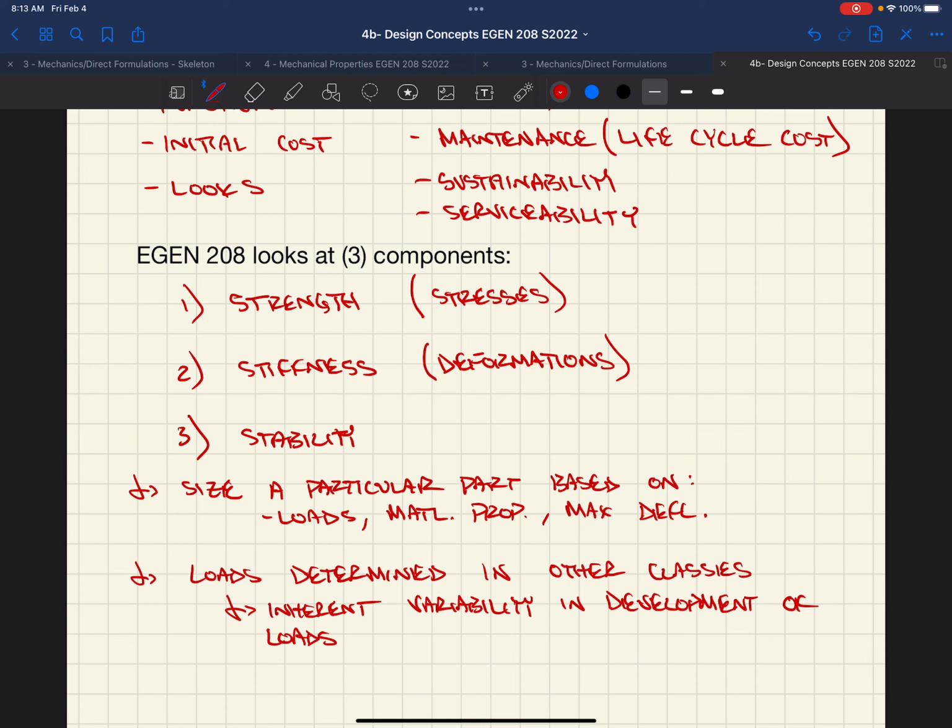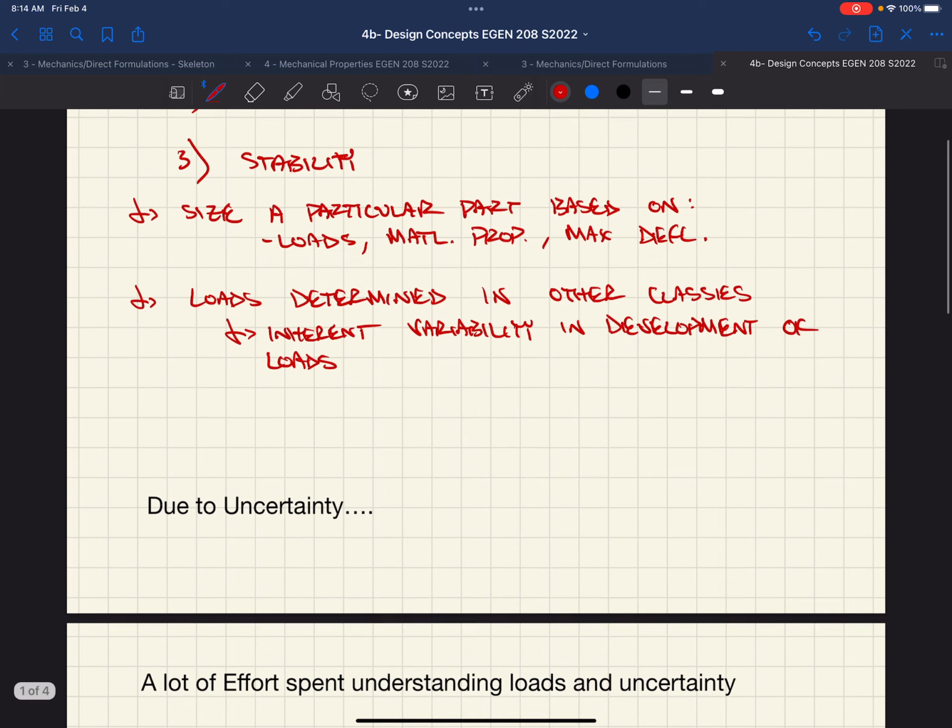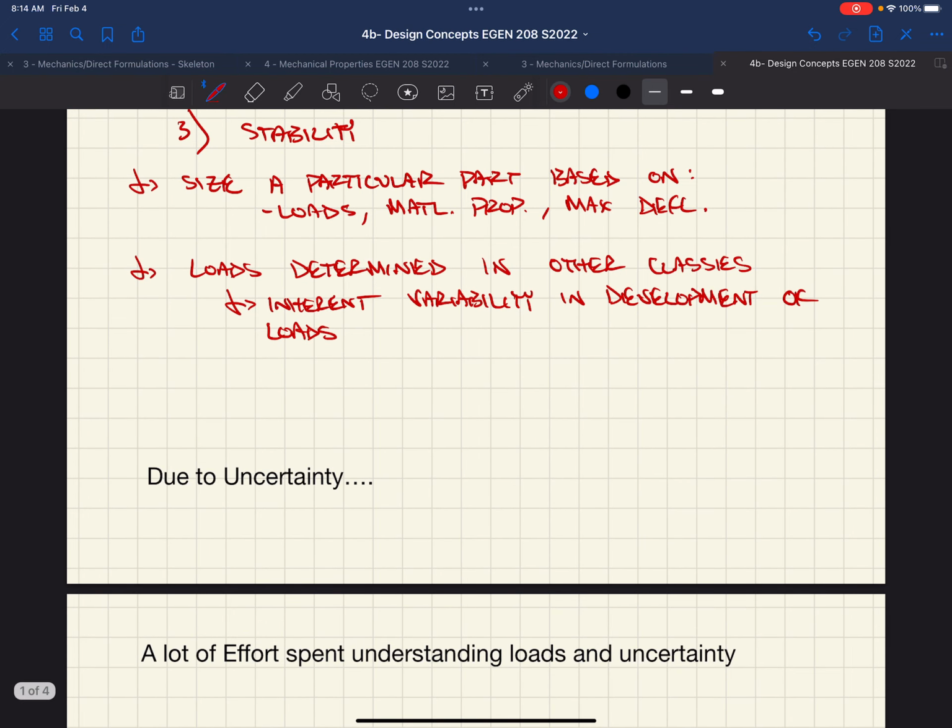We had 2 gyms collapse, and the snow loads that those buildings were designed to are not the snow loads that new buildings are designed to, okay? Those were designed for like 30 pounds per square foot, which is currently the state minimum. But if you're in the city limits of Bozeman, you've got to design for 40, okay? So inherently there's variability in loads.